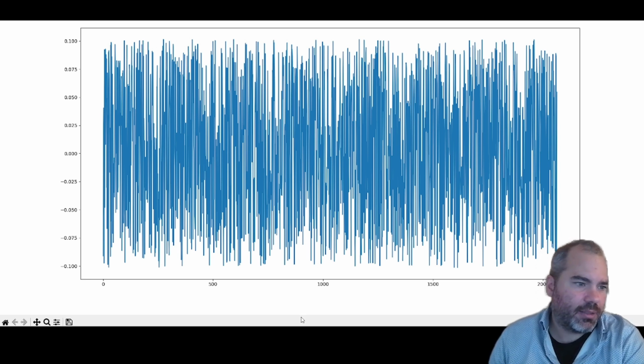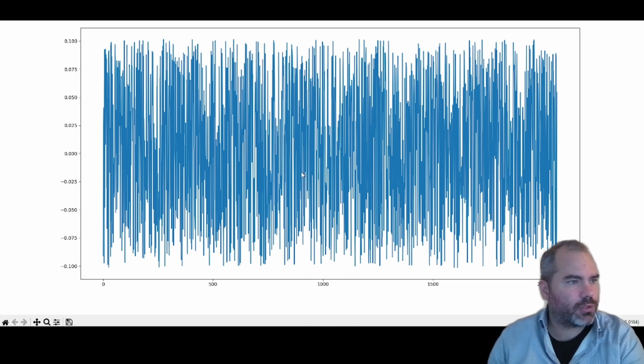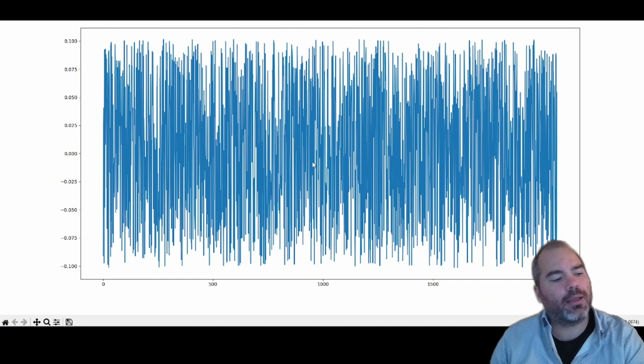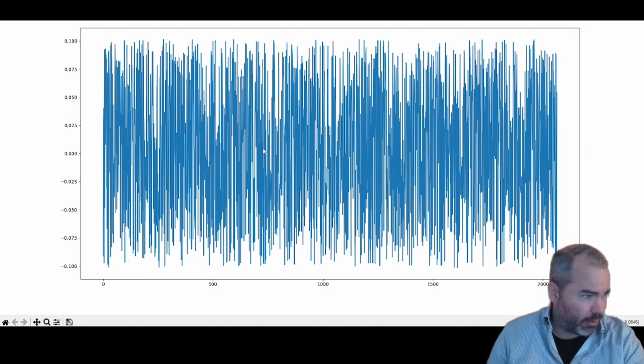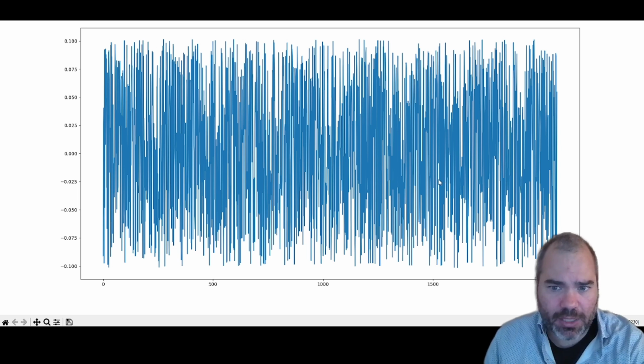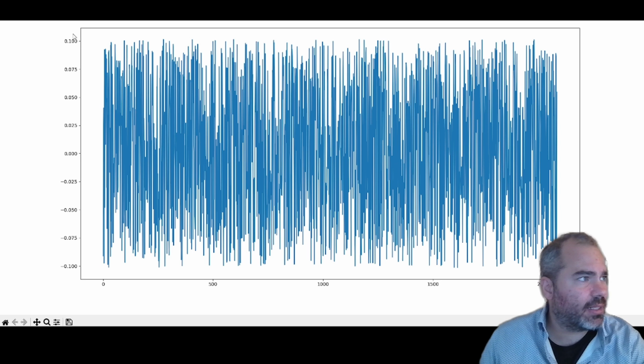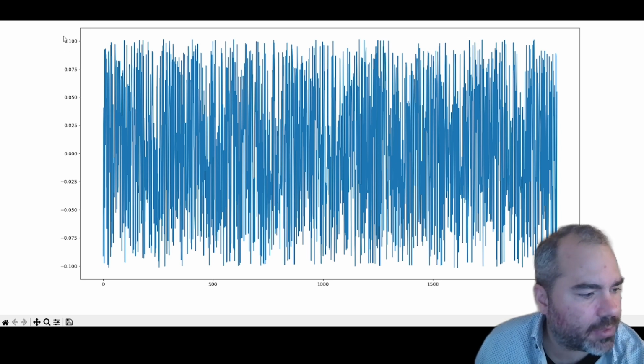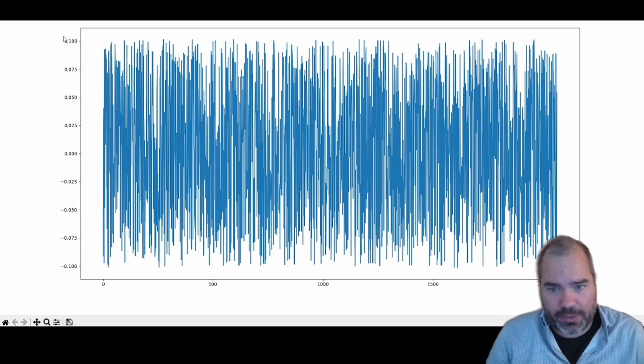The dev told me that this channel was supposed to contain a 0-centered 2 volt peak-to-peak signal. So it seems that I'm decoding something that is 10 times lower in amplitude than what is expected.